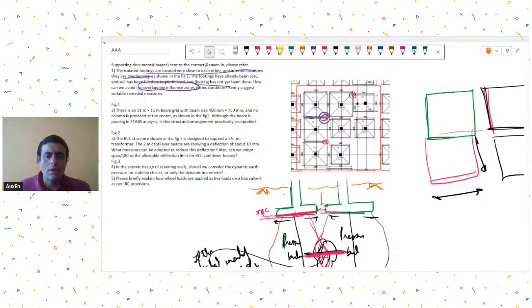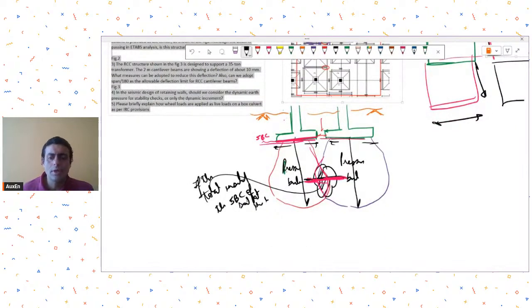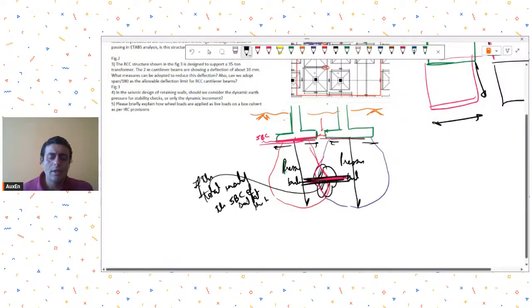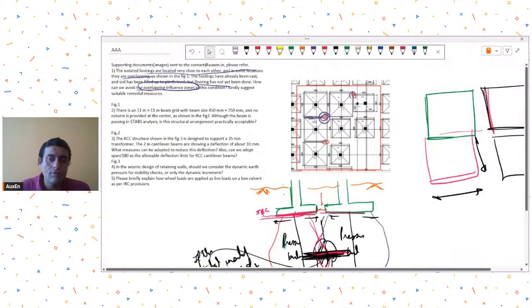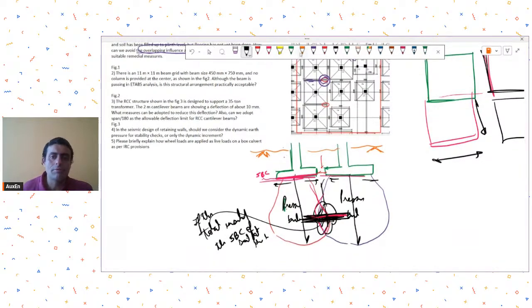So, suitable remedial measures, I would say: check with respect to this pressure bulb theory what's happening, and check it with respect to the bearing capacity at the level where the pressure bulbs are intersecting. And if you are getting a case where your combined pressure bulbs go beyond the SBC at this level, then you don't have much of an option left now. Understood?